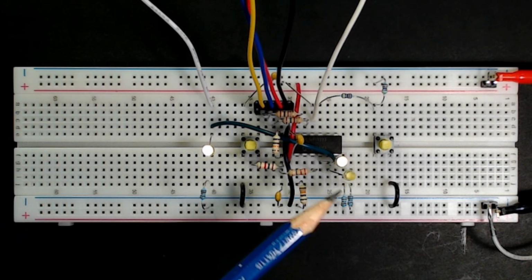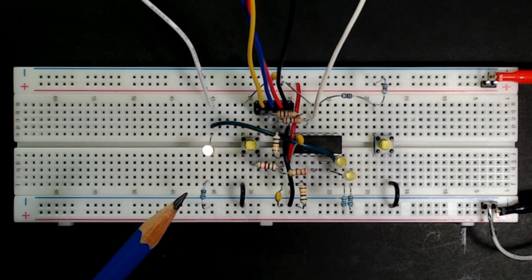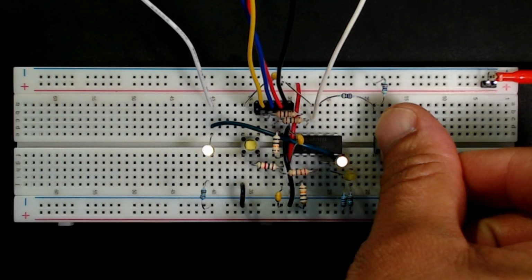And looking at our breadboard, we can see our 2 timer LEDs are going blinkety blink, which we're going to ignore from now. And there's our output LED, but notice it's on and I haven't pressed the button. When I do press the button, the LED turns off. See, this makes a lot of sense. Because of the way that we've designed our debouncing circuit, the button input on pin 2 is idling high when it's not pressed. When we press the button, we're grounding that input.